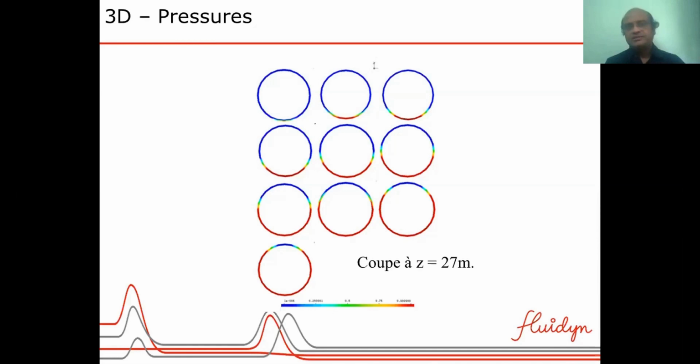So the complexity or the challenge to model this is that if you try to model water seeping into such small gaps, you'll find that you have to use very small time steps, a few less than a second. But as you know, we had to do the simulation for many hundreds of years, so we use proper subcycling and coupling between the different methods.